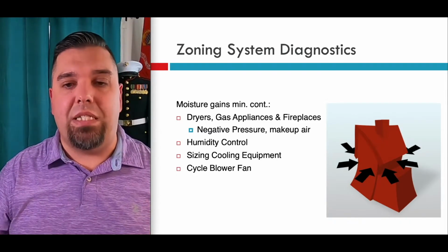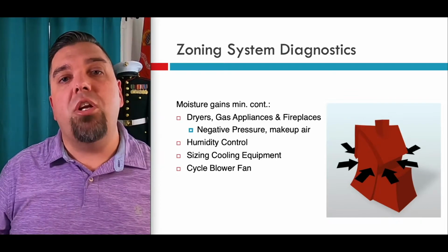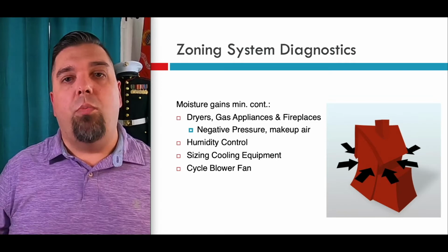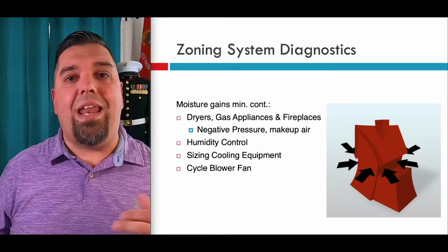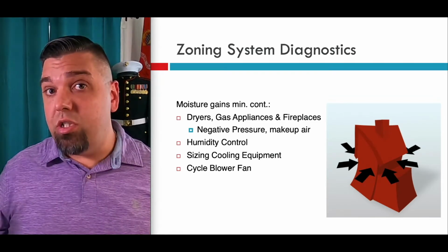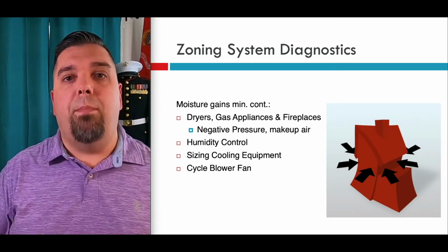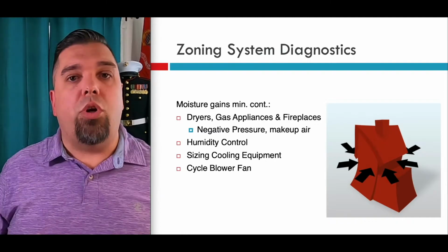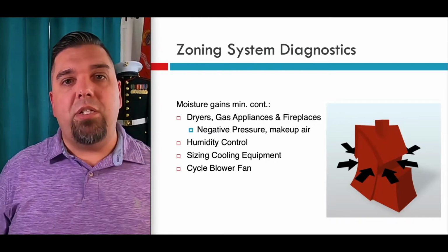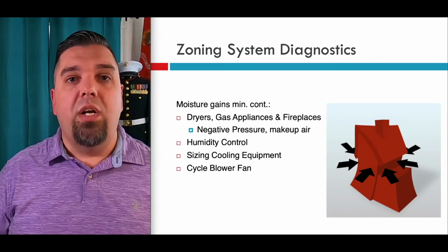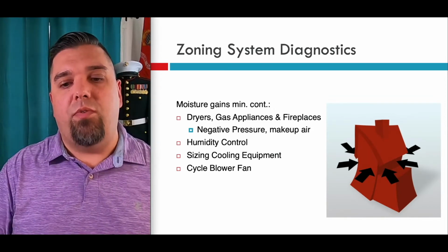So please make sure you do a combustion appliance zone test every time you address the home. If you're sealing up ductwork, adding ductwork, or adding returns because you're pulling a negative pressure from some space, make sure you test the combustion appliance zone so we don't hurt anybody in the house. It seems elementary. If you've never done it before, just head over to bpi.org. There's a great step-by-step process over there, all right?